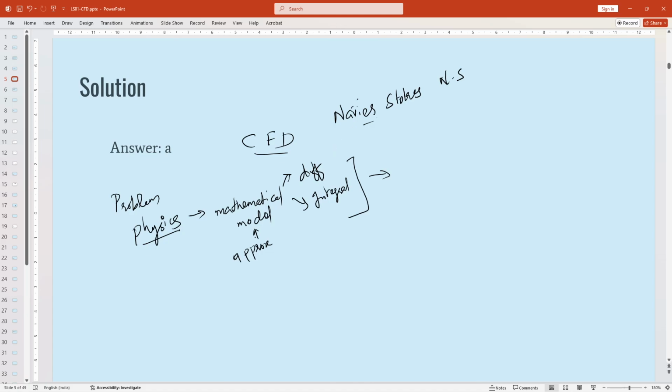So these equations, that is the physics, have to be expressed by the Navier-Stokes equation, and the Navier-Stokes equation is a big equation which we will discuss in the coming sessions. That has to be reduced according to the physics of our problem. So the initial conditions, boundary conditions, all those things have to come into the picture. Also, how the flow is. If you have watched the videos, in the first video itself the faculty is talking about axially developed flow. That is a reasonable assumption that through a rectangular duct, the flow in the axial direction will have the upper hand, so we are neglecting the other flows. That's a reasonable assumption. All such things should be considered while framing our equation to solve.